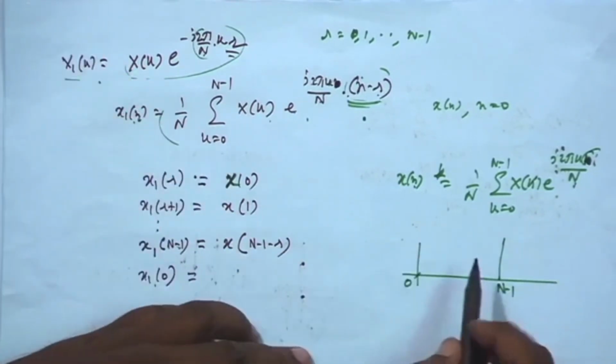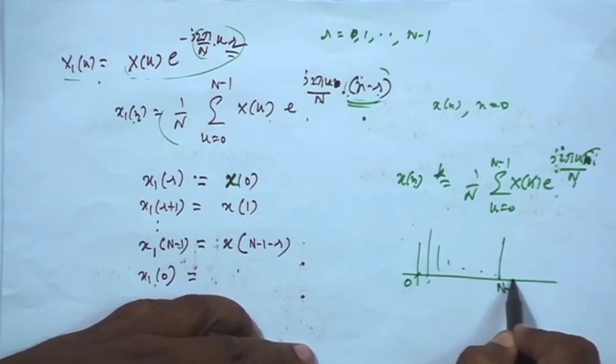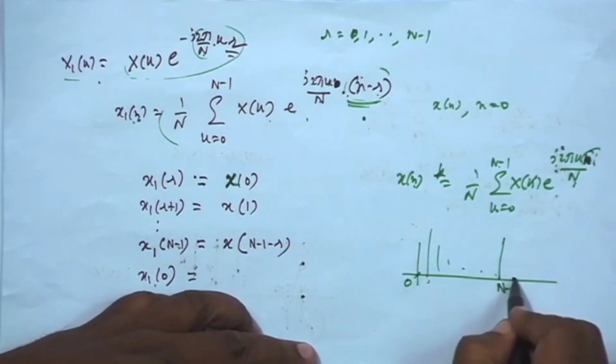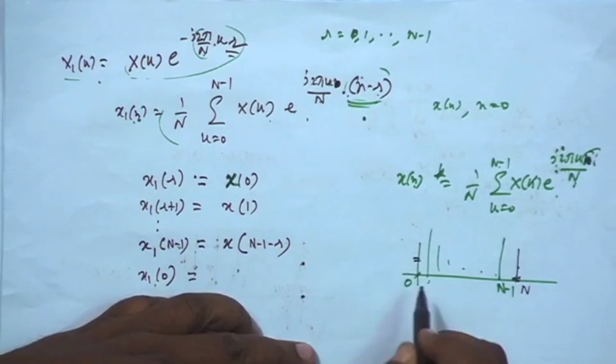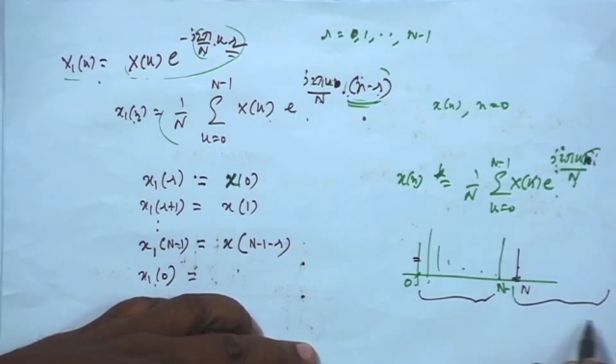if you take the inverse DFT and suppose this is a sequence, if you go beyond this, it becomes periodic. So, if you are going to the nth point, whatever you observe will be the same as at 0, 0 plus n. This block will be repeating, right, periodic.